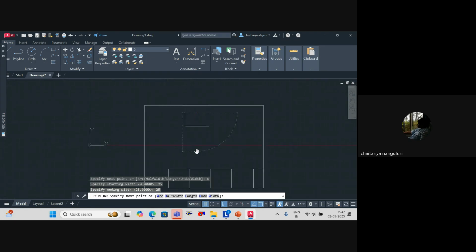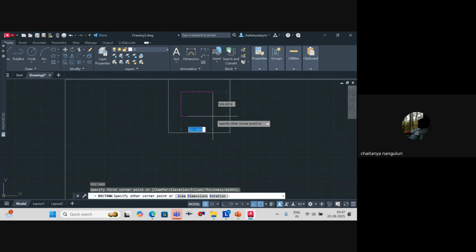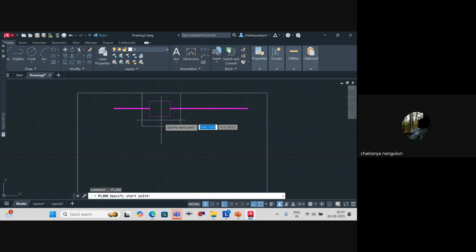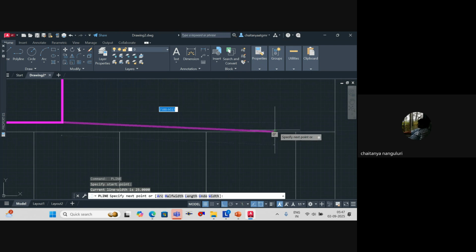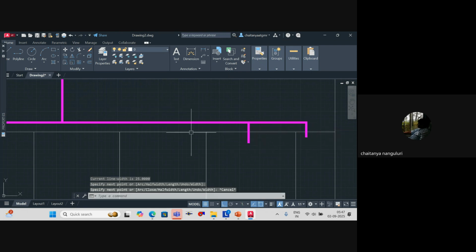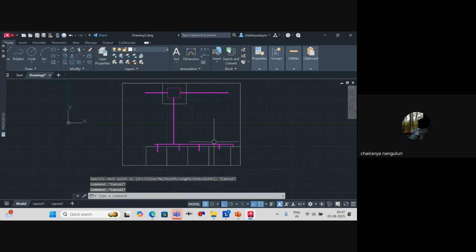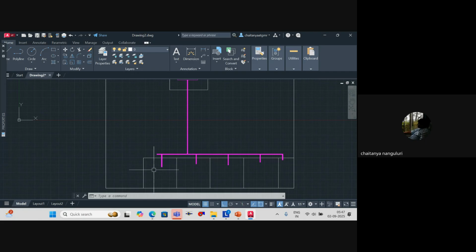Okay. So let's say I've done a ducting system like this. I've got a plenum inside, since it's a floor-mounted AHU. So from here, let's say one duct has come like this, one duct like this, and one more duct has gone like this, and then we have supplied air to every cabin. You agree I can do something like this? A distribution, or not? And for return, obviously, I'll keep openings so that the air will come above the false ceiling to this particular AHU.